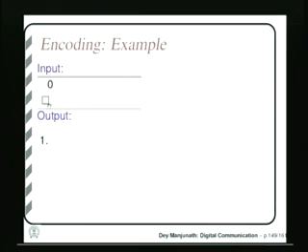So, we take the first bit, we have received 1. We see whether 1 is there in this. We see that it is not there. The only element in the list presently is null. So, we have got a substring in the buffer which is not there in the list. So, what do we do? We first encode the string which is preceding the last bit. So, that is nothing. So, null. Then we just take 1, that is the last bit.